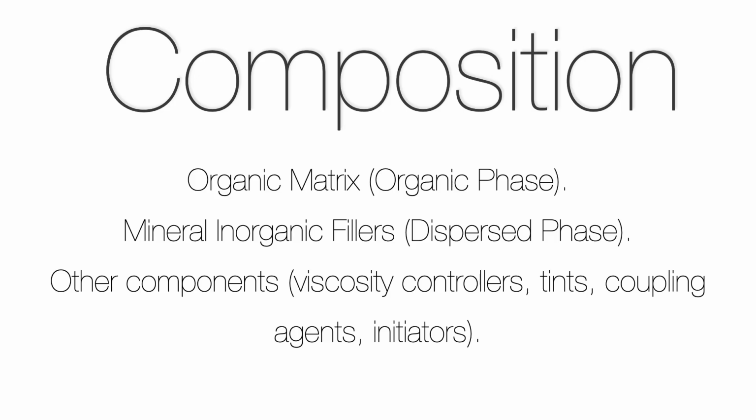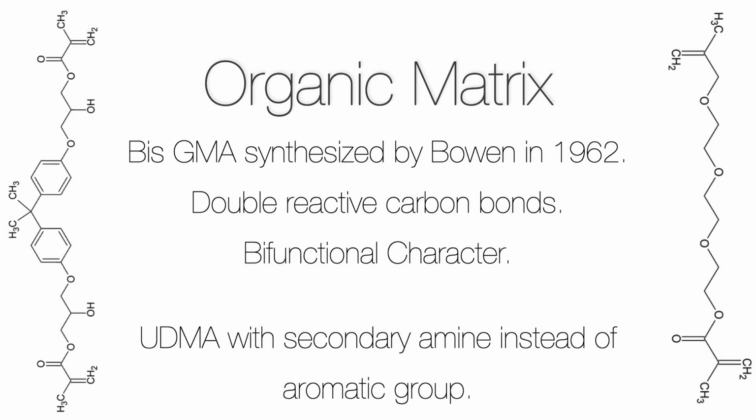We know that we have an organic matrix, which is the organic phase. We have mineral inorganic fillers, which is the dispersed phase. And we have other components: viscosity controllers, tints to do the color, coupling agents, and initiators. So the organic matrix is a mixture of methacrylates.